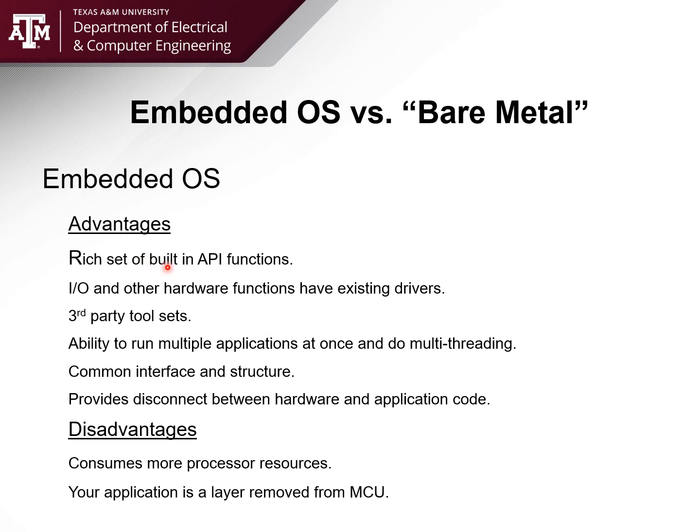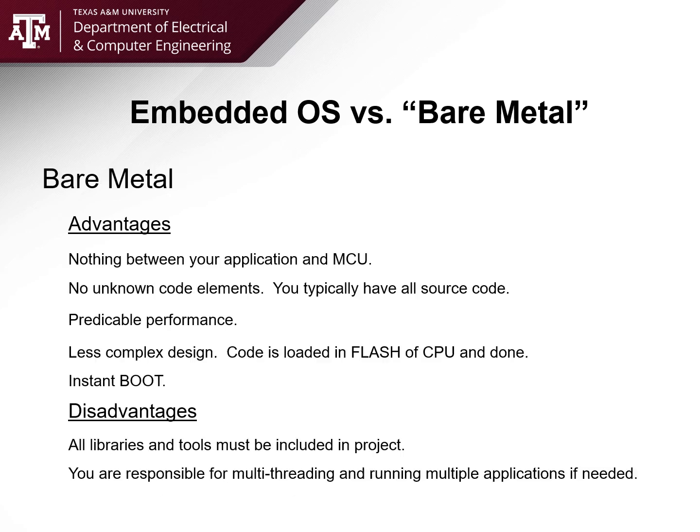Whereas if this was a little 8-bit PIC, I just read one register and turn on and off one bit. Basically I have this monstrous load of embedded Linux to end up doing what literally 4 lines of code on a Microchip PIC do. So you have to weigh whether or not that makes sense in your particular product line.